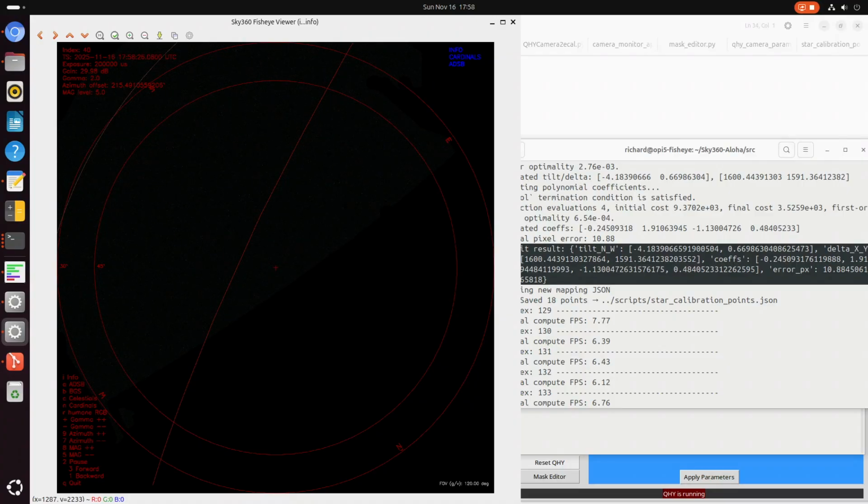And I think we discussed this in the past, and we came to the point that the ring buffer is the easiest way to do this, so that every sensor creating data is putting the data in a ring buffer, so that we can flush this ring buffer to disk in case of an event and have the history included. What do you think, Carlos?